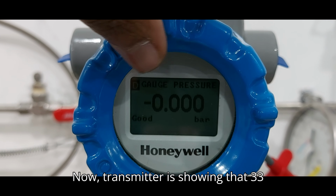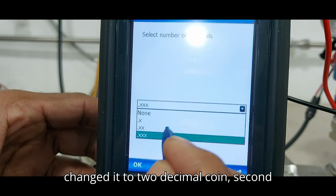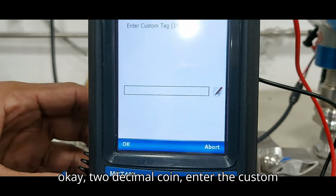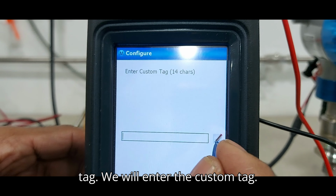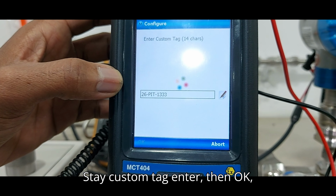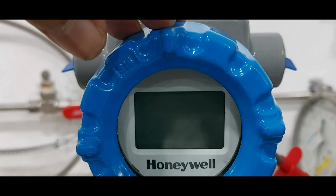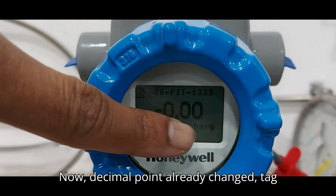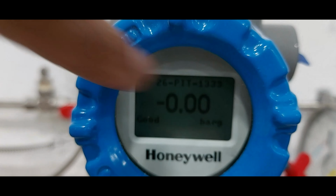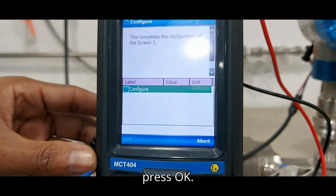Now the transmitter is showing three decimal points. Now we change it to 2 decimal points. Okay, 2 decimal points. Enter the custom tag. Then OK. Wait for 30 seconds. Now the decimal point has changed. The tag number is also showing on the display. Display configuration is completed. Then press OK.